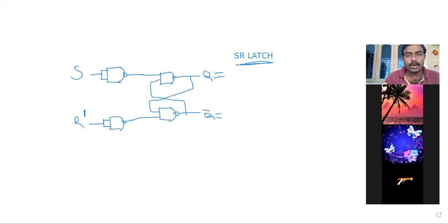Let me see how we can carry out this operation. Guys, now I am taking S equal to 1 and R equal to 1. If 1 is passing through the NAND inverter, I am getting 0. And if this one is passing through this NAND inverter, I'm getting 0 again. Let us assume that 1 is available here, guys. That one will be reaching this place.